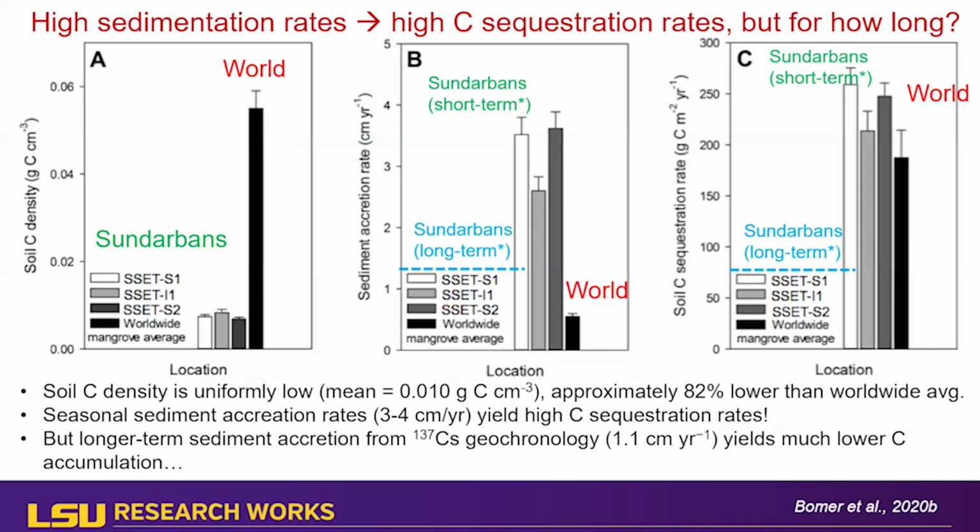Okay, last slide. I'm going to wrap it up here. I just want to mention we not only have seasonal inundation and vertical accretion rates, but long-term ones. And it's important to note whichever one you use, that could give you a different carbon sequestration rate. So if you're looking at short-term sedimentation from sediment tiles, you could say it's on par with the world. But if we're looking at the longer term, what's in the core, it's actually a little bit lower than what's been reported elsewhere. Thank you.